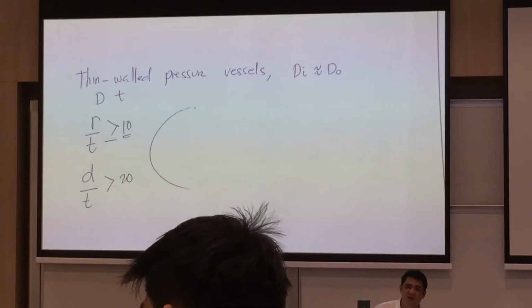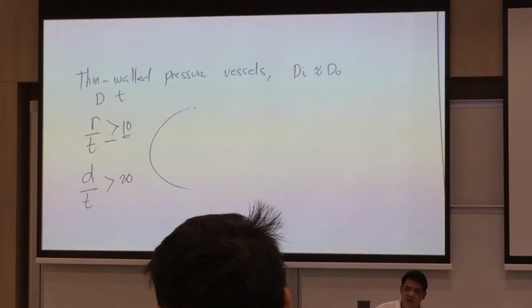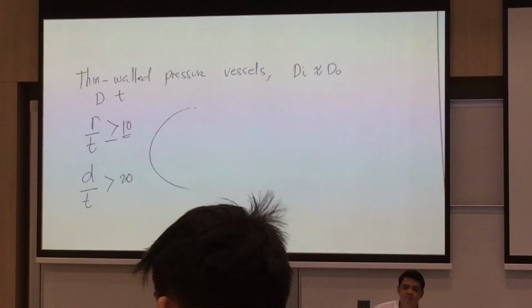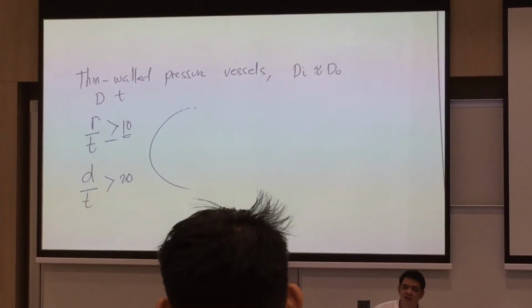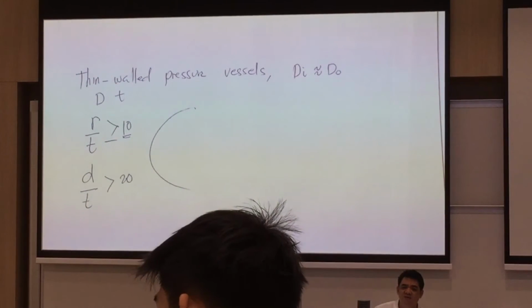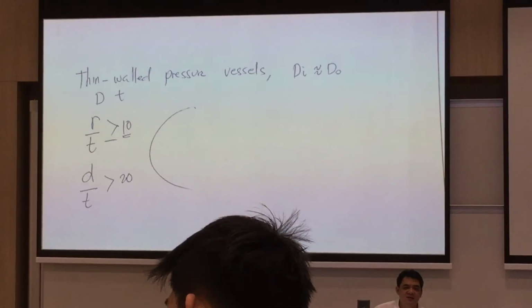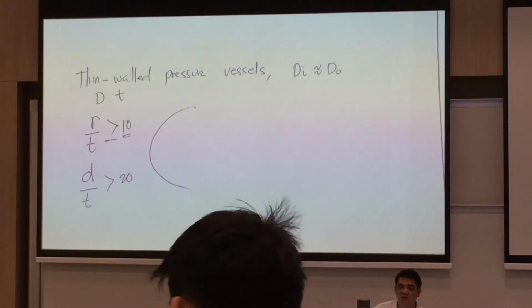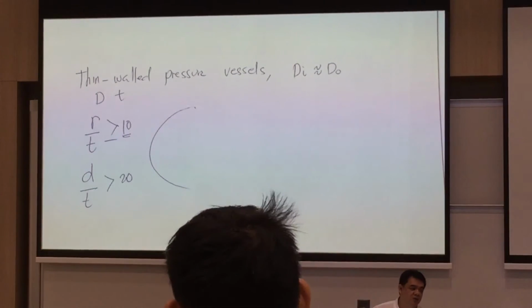So here you have a thin-walled pressure vessel wherein we want to know the stresses acting on this one. So how do we begin with this one? So we use the principle of statics. Equilibrium of forces along the longitudinal direction is equal to 0.